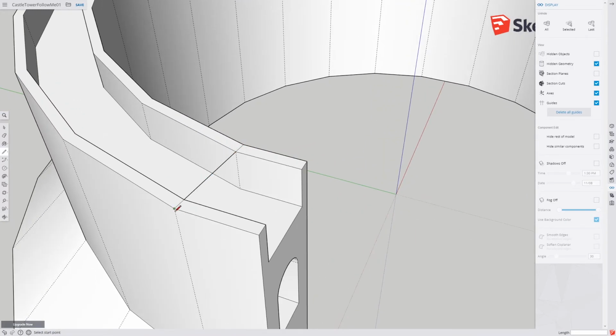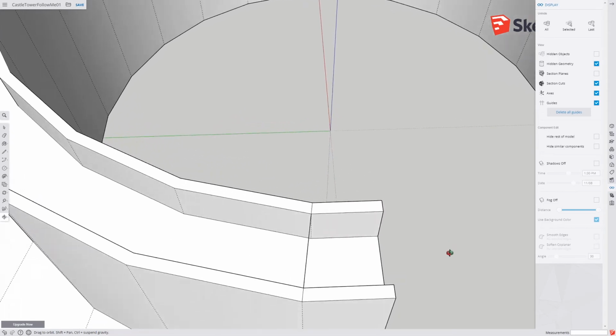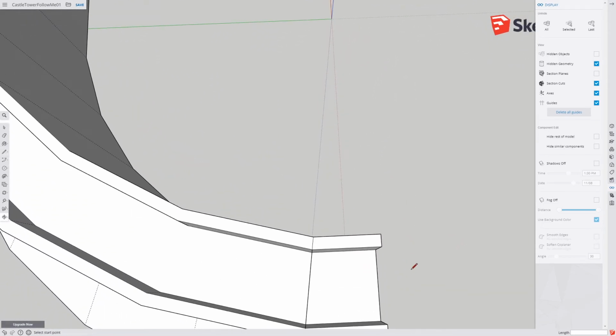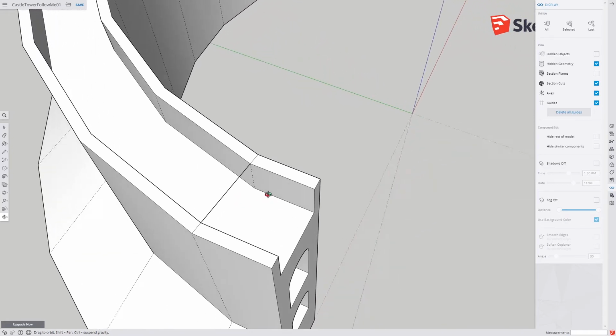So I've come from that point to that point, and I'm just going to bring it out maybe 200 and 200. So let's use the pencil tool again. Remember, I can't draw a rectangle because we're off there. I could rotate it and do all sorts of things, but let's do it with the pencil tool. Bring along that edge, type in 0.2, which 0.2 of a meter is 200 mil. There it is. If I bring it along here, see how it goes different colors? Purple should mean it's parallel to that line, but it's not wanting to do it at the moment.